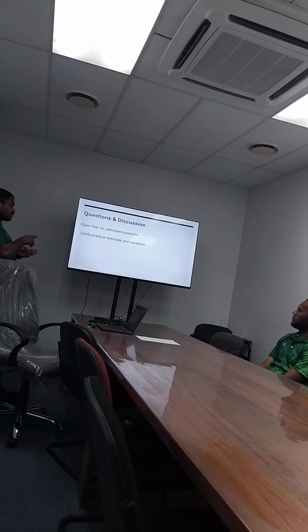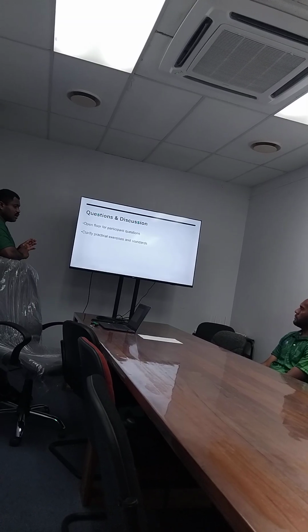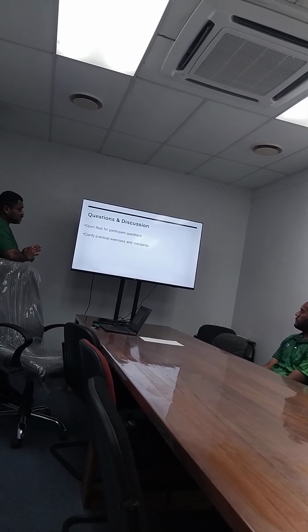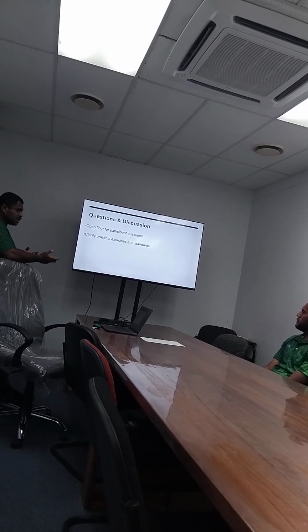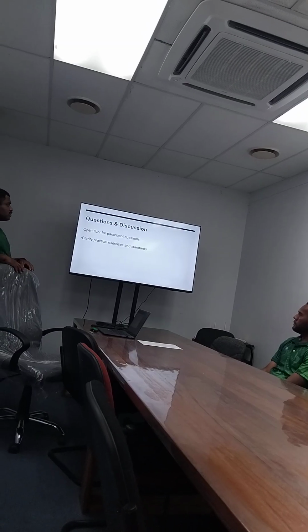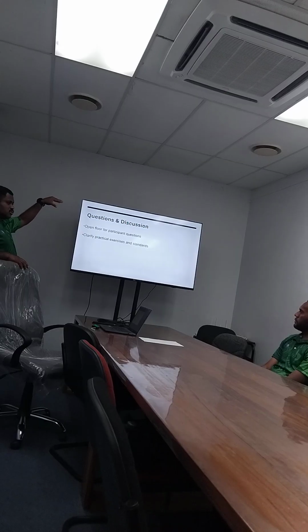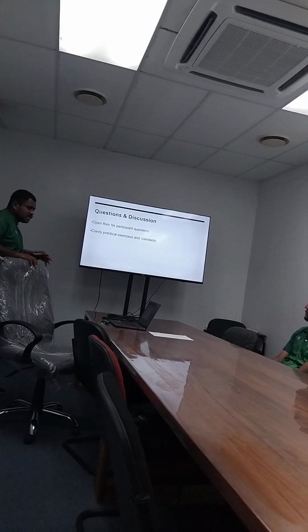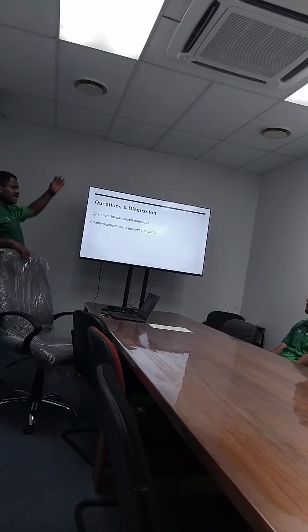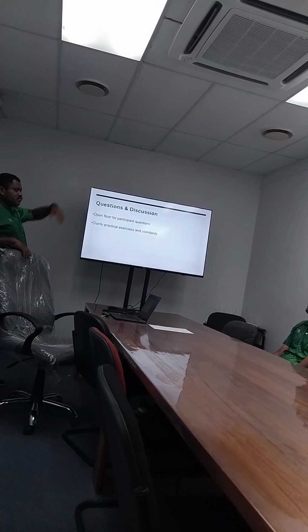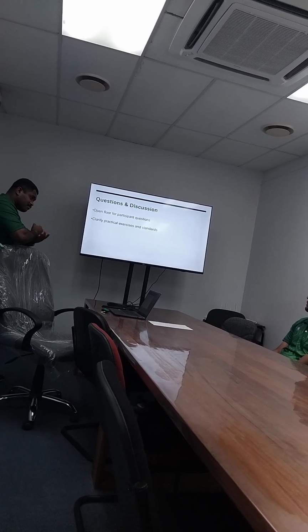We have gone through faults where the GPS antenna had been faulty. Too much rain, water seeped into the antenna, shorting the antenna. There was no position. So when we came up to the RPU, the GPS data is connected to the RPU of the computer. There was no GPS data coming from the GPS antenna, so the RPU was lost. Any message sent by the aircraft was deemed invalid. They couldn't process it because there was no timestamp.